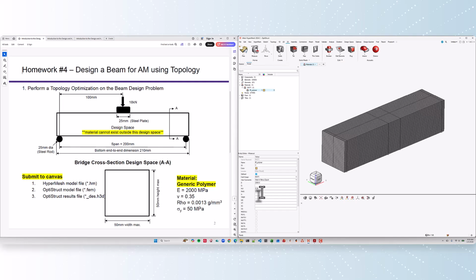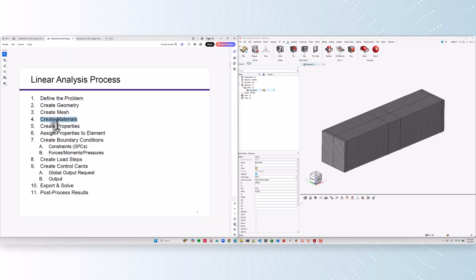And then to be consistent in millimeters, grams, and MPa, my load has to be newtons. So I have to, when I go to do loading, I have to change that 18 kilonewtons into 18,000 newtons. Okay, but I got that part done. So let's work down our process. I need to create properties. So create a property. I just call it solids. Call it anything you want.